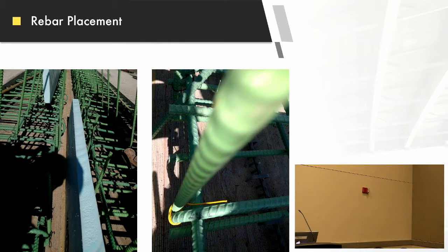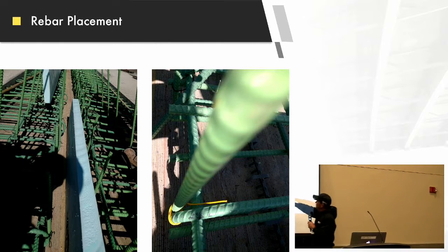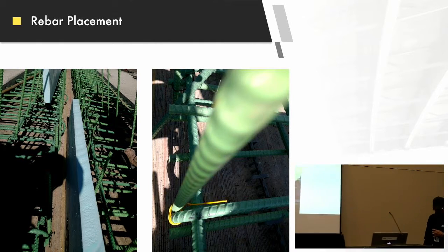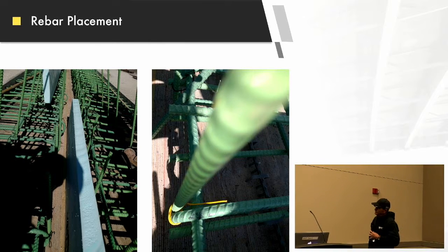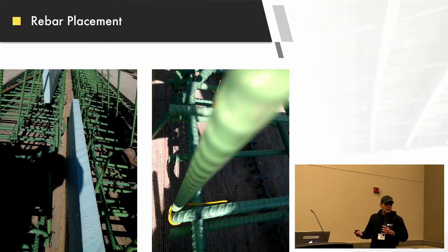This one here is just a quick shot of some rebar that was obviously damaged. There's a few of them in there. On these, the contractor will come out with their green spray can, spray a single coat over it and call it good. That's not good enough. We really should be making them use the two-part epoxy paint, watching the cure time on the epoxy paint before they place the concrete. Again, if you leave that little nick in there, it's just going to propagate through the rebar.